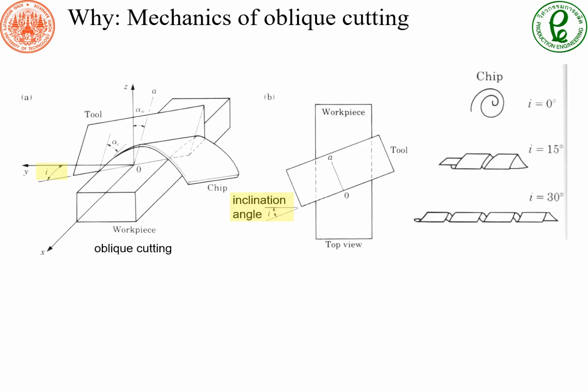Most of the time when we do the cutting, either the cutting tool is rotating or the workpiece is rotating. By having either the tool or workpiece rotating, the tool is actually slicing into the workpiece. That slicing action is called oblique cutting. The inclination angle makes sure that the tool is slicing into the workpiece. This slicing action also creates smooth, uniform cutting chips.